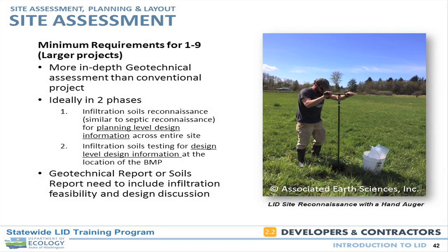where we do, just like septic, we go out and we do a reconnaissance level soils assessment with some hand augers. We poke a lot of little holes around, we review maps, we go out and confirm, we see what we're up against, and then we maybe do a conceptual site layout, and then we go back out and collect our design level information. So really there is a reconnaissance phase and then more of a design phase.